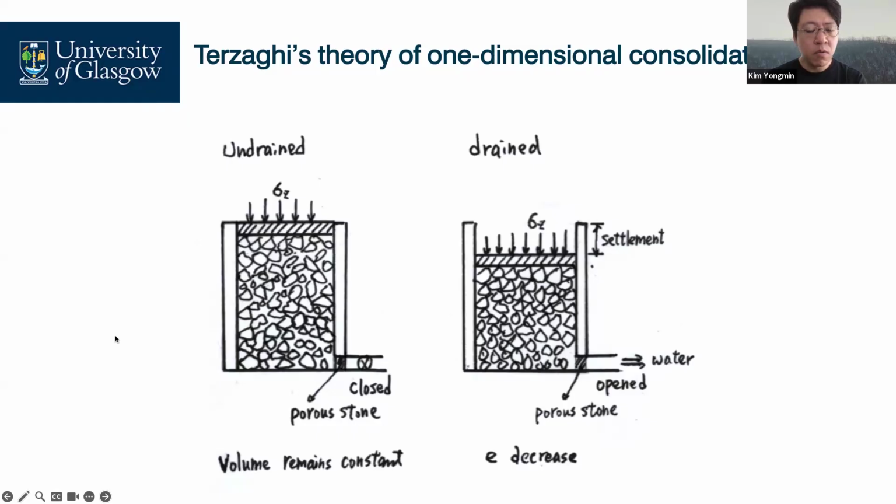But what situations are undrained conditions? For example, consolidation takes 1 year, 2 years, more than 5 years, something like that. It's quite long term, right? But say I want to construct a coffer dam for pile installation in only 1 year, 6 months.